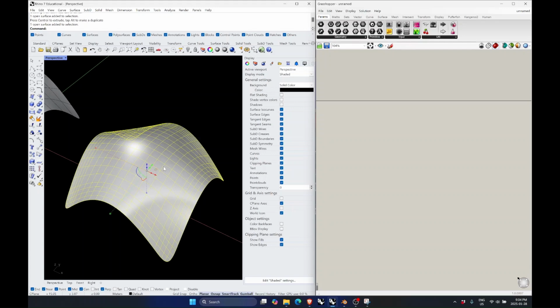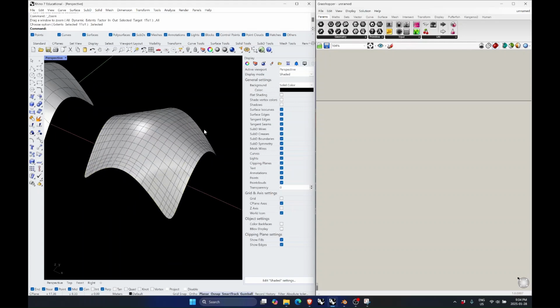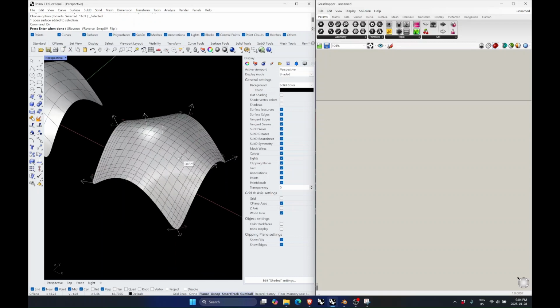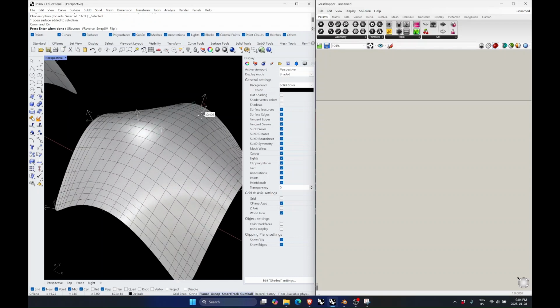And then let's get into some of the basics of this NURBS surface here. So if I was to press DIR, this shows me directions. Now, as you can see here, the white is typically your normals. I believe the red, let's see, U reverse. Yeah, so the red is my U direction. And using this, you can reverse the direction, but right now I'm going to keep it as it was. V reverse is the green direction. So again, I will keep it as it was.